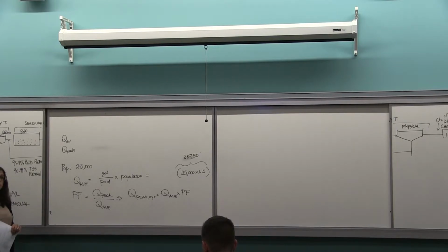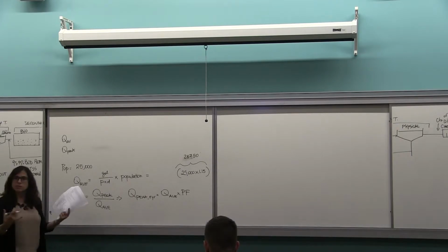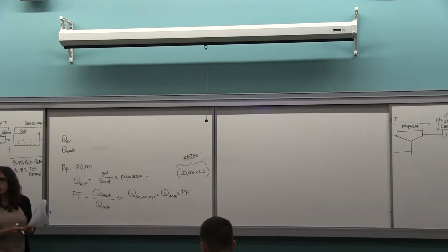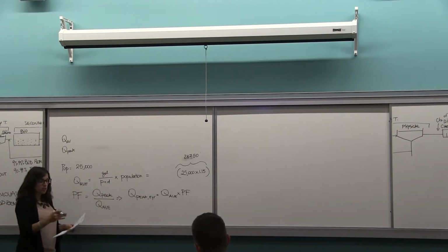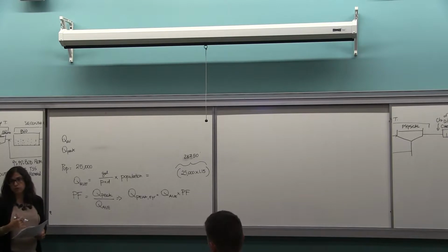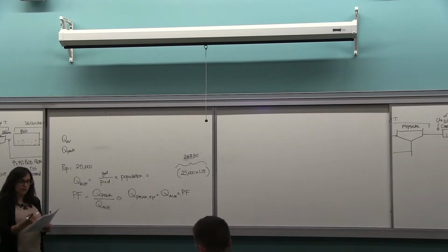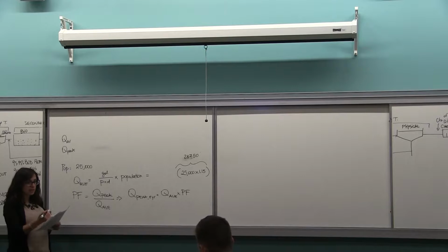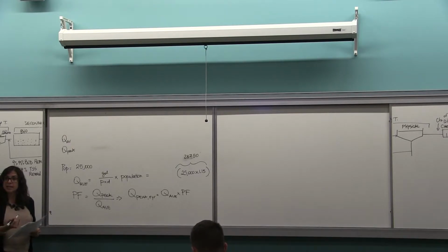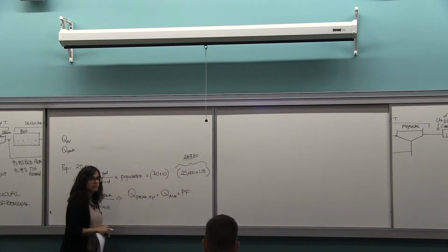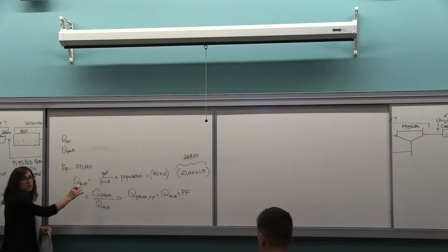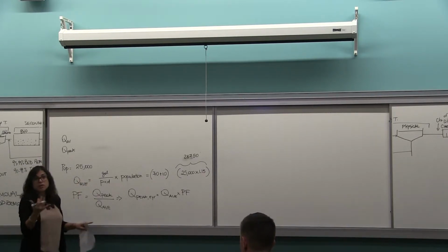What is the water use? When we talk about population, it's population equivalent, so it's considered the number of people overall in the community. For the gallon per person per day, we need to consider in this case both the residential and commercial. So for that information provided, we have 70 gallons per person per day plus 10 gallons per person per day. That's going to be our water use, water production, right?